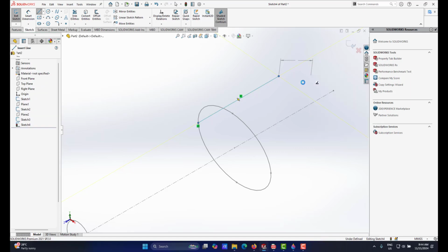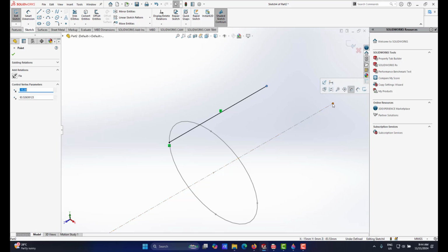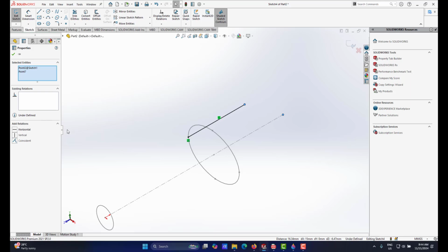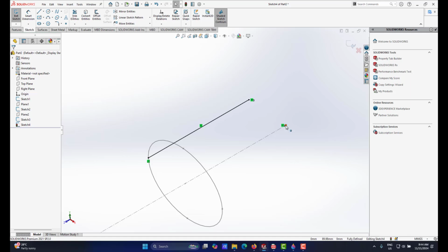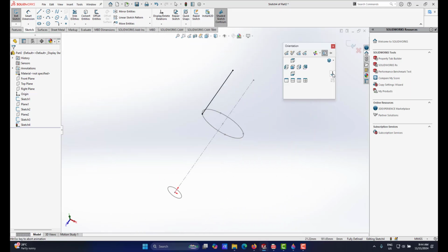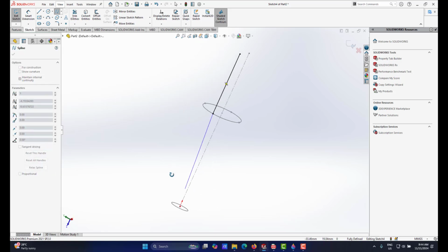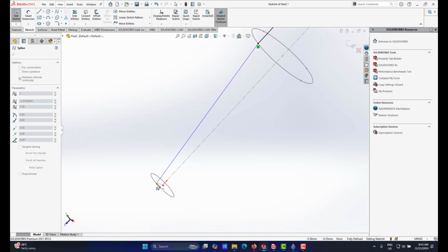Okay. And here, I must make sure this point and this point are in line in terms of the level here, so it will be horizontal. So it means maintain in line with this endpoint of the main axis. Right, if I go to perpendicular view or normal view, I would create a spline here from this point and make sure that it snaps.